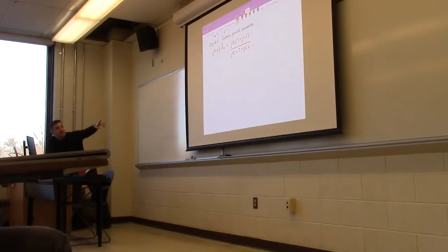Because the second element doesn't have real and imaginary components, multiplying out the j will only take 2 seconds. Whereas if you had two components, you would have to multiply it out and then combine the real and the reactive, and that becomes a whole pain. But we can just multiply the j out, so it'll end up being j15 times 7 minus 2, because j times j is equal to -1, and that'll be then minus 15 times 0.2.